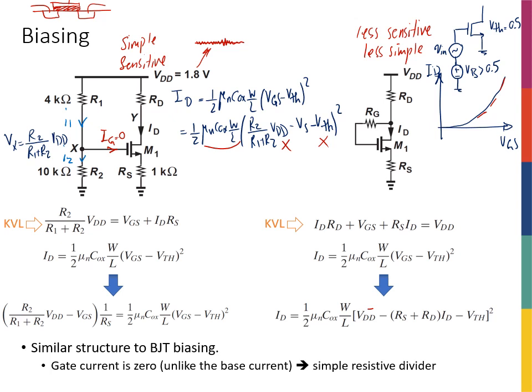So you design your transistor and your circuit based on the model provided by the fabrication house, but then you send the circuit to fabrication, and it comes back and the mobility is not exactly the value that you wanted, or the W and L that you drew in your physical layout are off by a few nanometers. So I might have variation here, in VDD, and in threshold voltage. Okay. Now, why is that important? Because they're directly affecting my current, and there's no process to stop them, control them, or attenuate their effect.